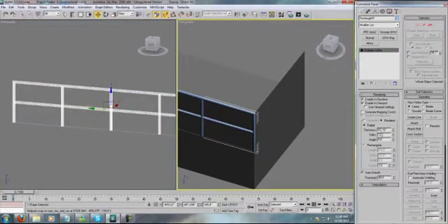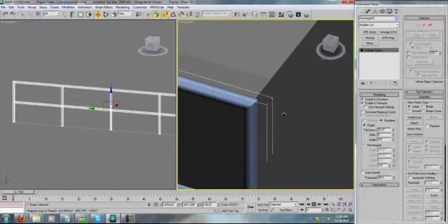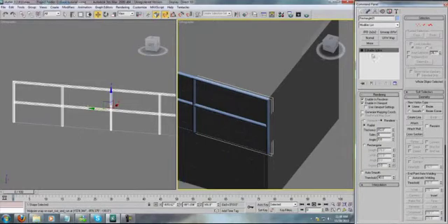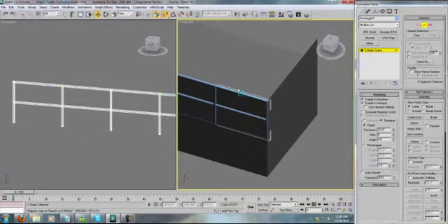Let's go in and give this 6 sides and a width of 2 inches. 6, not 100. Let's also turn off auto smooth. What this does, as you can see, is it gives a smoothing to the polygons. So what we want is for this top spline to continue along this edge here.